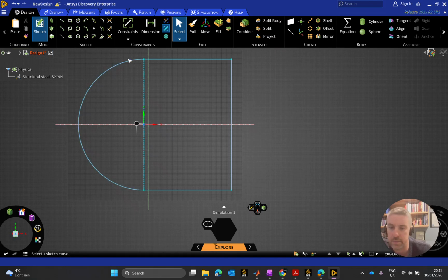So again, this is what's called, by the way, a D-type domain. You could have a rectangular domain, a square domain, an H domain, I believe they called it officially, and that's just square. Why didn't I use it? Well, there's really no need. If you make an H domain, it'll work fine, and I can just bring my air straight in.